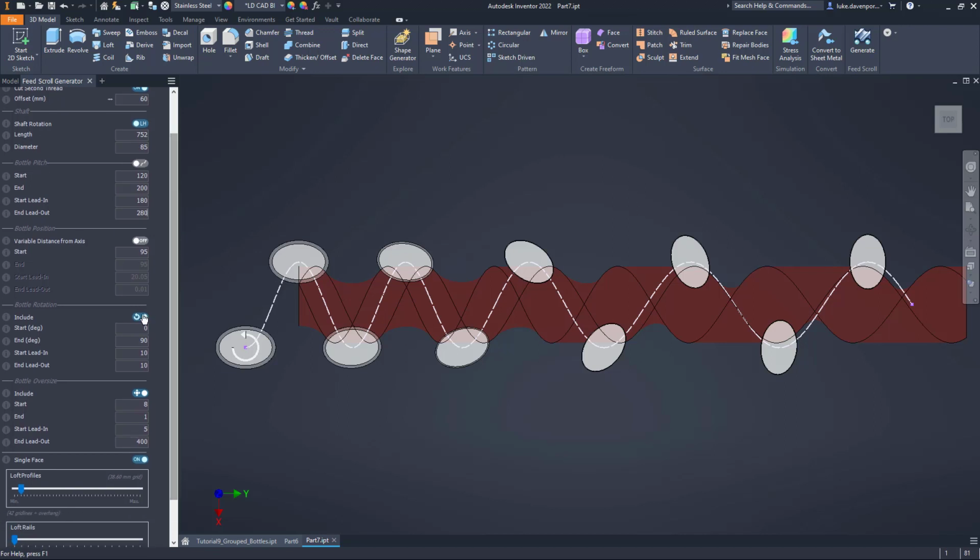And also, actually, what I see here is that the bottle hasn't fully completed its rotation here. It only has by, it looks like it has here, close to the end of the shaft. I should really have increased these values to start the bottle rotation maybe a bit later and finish the bottle rotation maybe a bit earlier. I should have increased these values, but we'll leave those for the moment. So let's try a value of 280 here. We might get a slight overlap between these two bottles at the end, in which case all we have to do is just run another quick build and fix it.